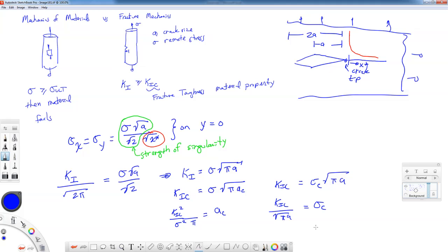That's why in aircraft they monitor crack sizes. Once a crack reaches a certain length, then they pull that part out of service, and then they repair it or replace it, and then they start it over again, and they monitor the crack growth. You don't have to throw the part out if the crack is too small, but if it gets to a certain length, or before the next inspection interval, it would be anticipated to get to a critical length, then that component is pulled.